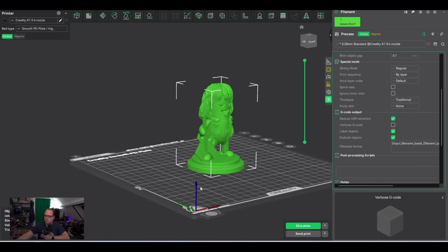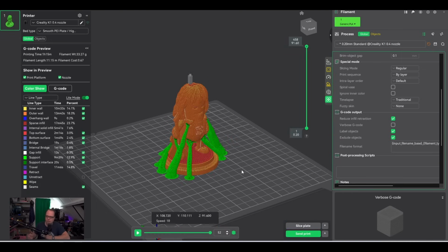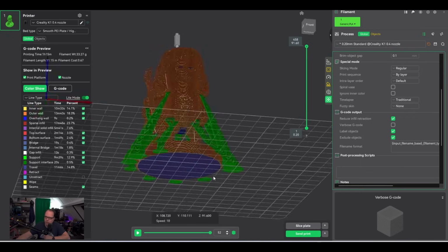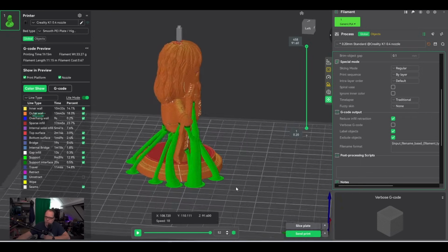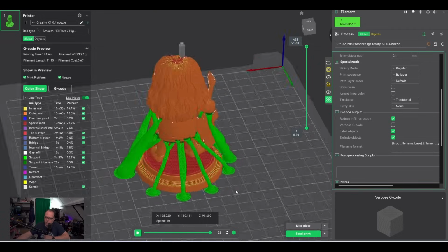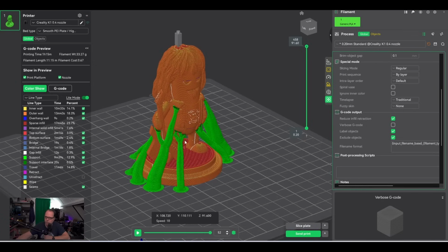I'm happy with the result here, slicing the plate. It takes some time. After a while, it's done and it's sliced. So, like mentioned, here are the 3 supports. Like mentioned, not touching the base of the model, but touching the build plate itself. And then growing all the way in order to touch the model where the supports were needed. Now, once that is done, I can send the print.